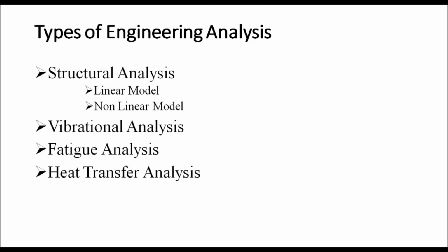Then, if you take fatigue analysis, this analysis helps designers to predict the life of a material or a structure by showing the effects of cyclic loading on the specimen. This analysis can show the areas where crack propagation is most likely to occur, and failure due to fatigue may also show the damage tolerance of the material.